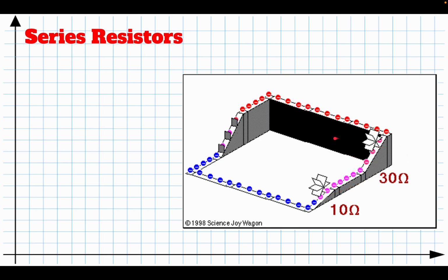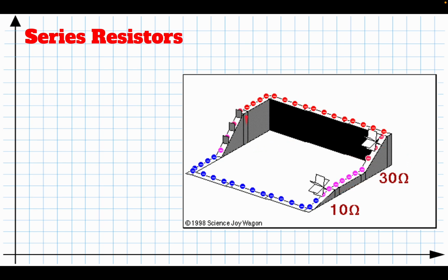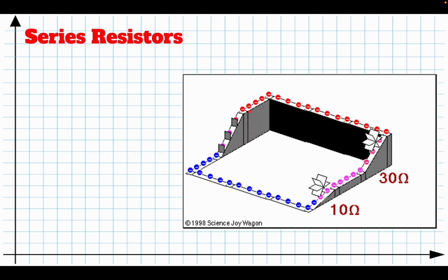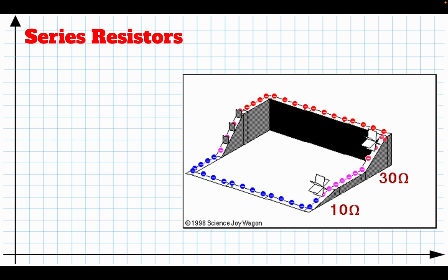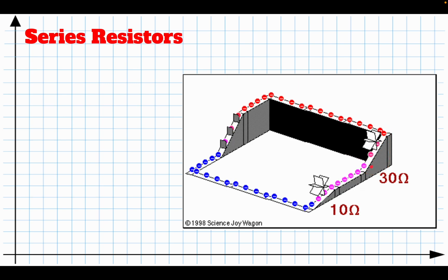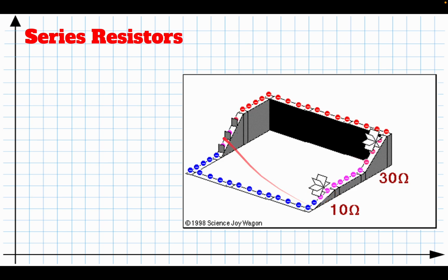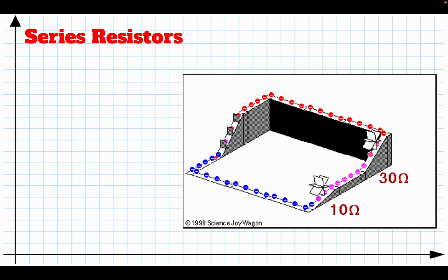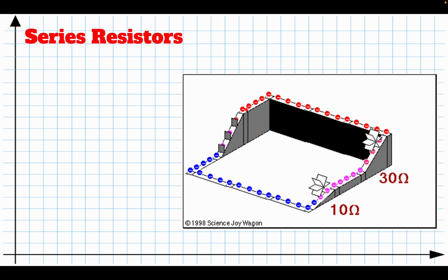Okay, now, the energy, the voltage. So here, this adds some voltage. Let's say this adds 9 volts. That's 9 joules of energy per coulomb. So these guys have 9 volts. They might lose 7 volts here, but if they lose 7 volts in this resistor, then we know that they must now lose 2. Because if you add 9 volts, sooner or later they're going to have to lose 9 volts of energy to get back to where they started, right? So because this is a closed loop, whatever you gain, you have to lose.